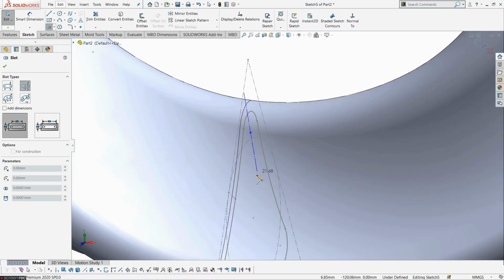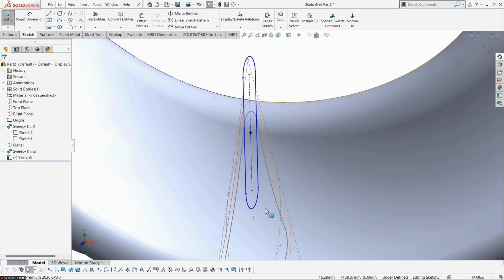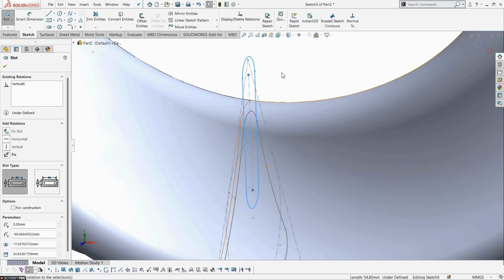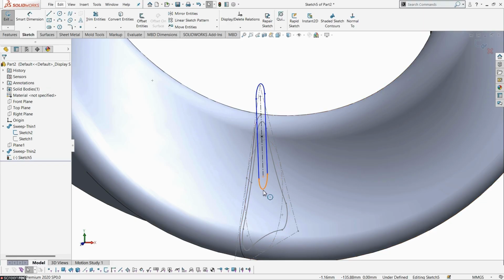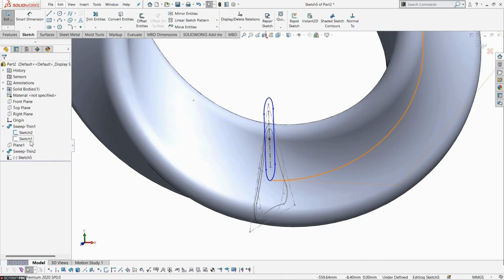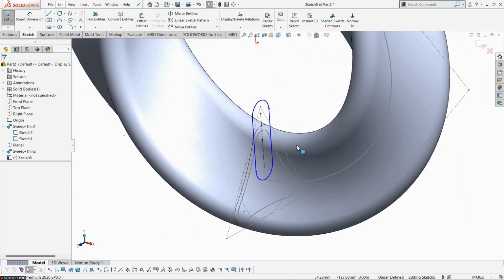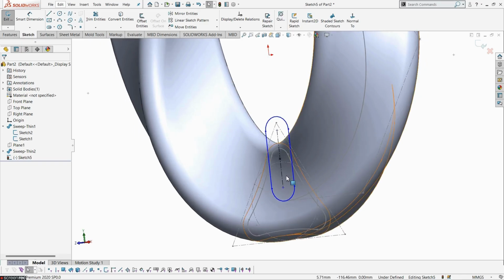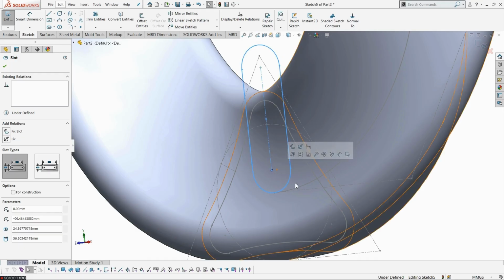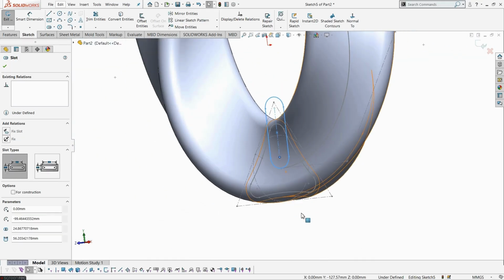Look at this control of one portion to another. Once it is properly fixed, then use the vertical constraint to fix it linear. Now it is maintained with each other. Afterwards, we need to fix it by using a smart dimension value also. Also, it coincides with the center point of this primary profile itself. Now show the path curve also, because we need to position the profiles at the correct endpoint. So selecting this curve, it is already positioned at the curve itself.